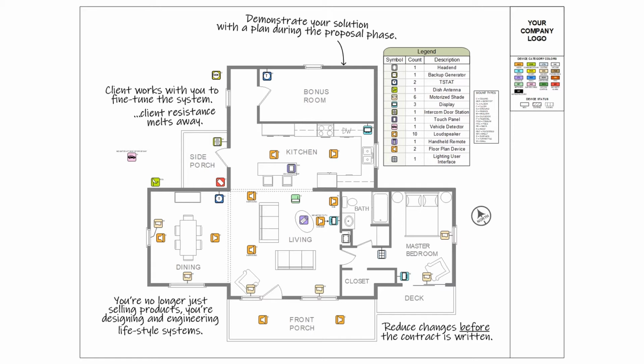One important note: The pre-wire can be shown on this AV floor plan, but there's a good chance you'll miss one or more wires. And this is because not all project devices are shown on the floor plan. Remember, the AV floor plan is really a conceptual drawing showing only key devices that the client needs to see, not a full design. And that's one of the reasons why we need a full system block diagram as well.